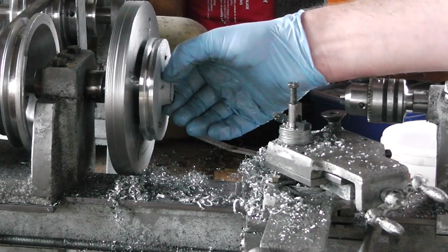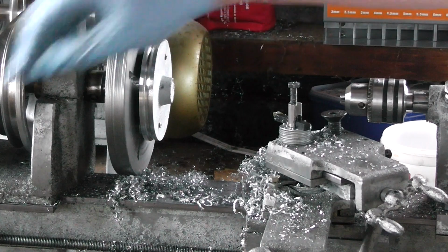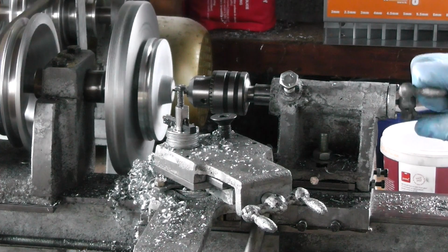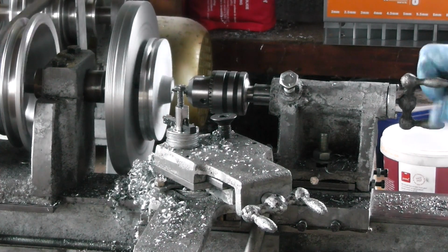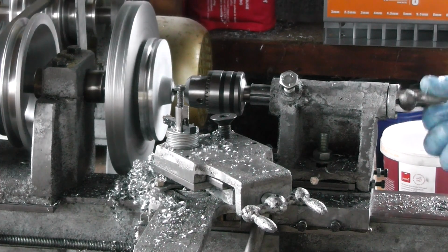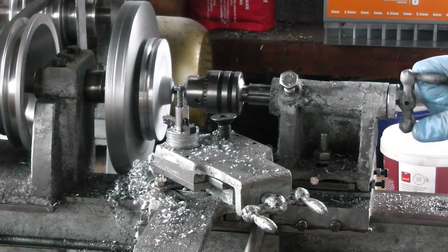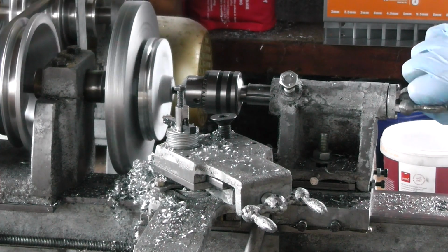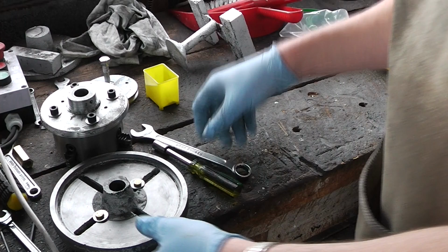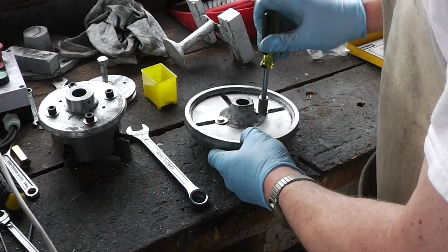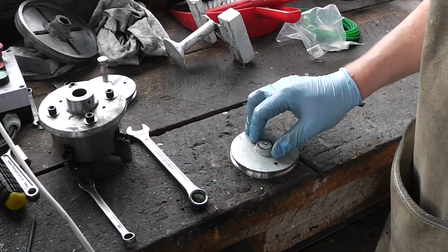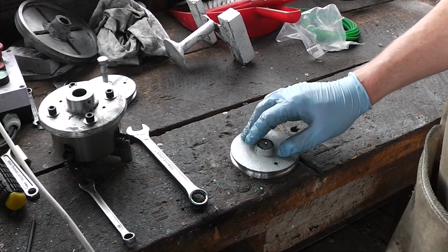To turn this centre part, because this will be going here, the pulley will only be going on the big one. Cleaning the floor is the really annoying part. Alright, let's take this off. Because this will be going on the lead screw, I think I'll drill it out to 8.5 and then tap it for M10.